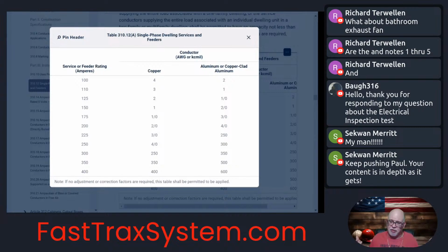And you're usually never going to have more than 3 current-carrying conductors for a typical service, especially a residence. So that usually doesn't come into play. But the ambient could come into play, but ironically, I just don't see many people taking it into account, but you're supposed to. On an exam, it could come into play. So be aware of that.